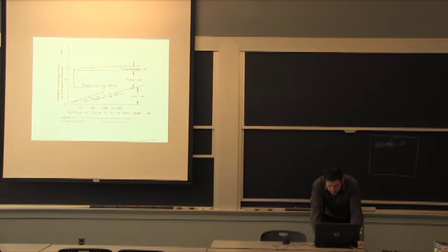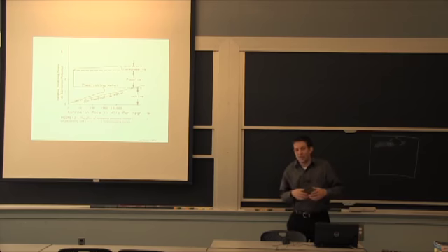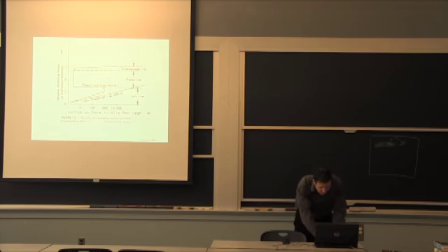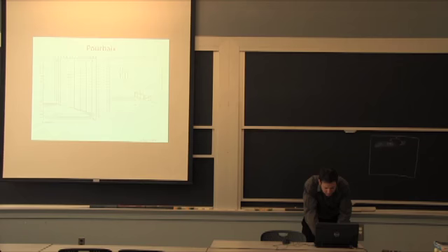We talked about active and passive. Essentially, stainless steel comes out of the mill with a passive layer, but when you have an attack, any kind of pitting attack, you lose it, and that's where you start having a very high corrosion rate. We're looking at the corrosion rate here in the active zone that is more than 100 times, I'd say even 500 times, as high as in the passive state. So by all means, you want to avoid it.